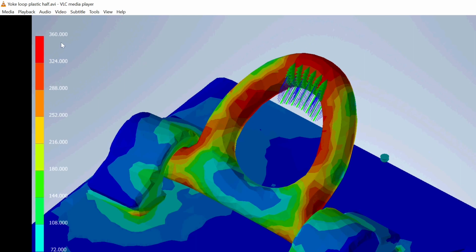This red area has stresses above 360, which is the limit, and then that produces a risk of pull through, so the attachment might get disconnected by causing this area to fail and just sliding out once it opens up.